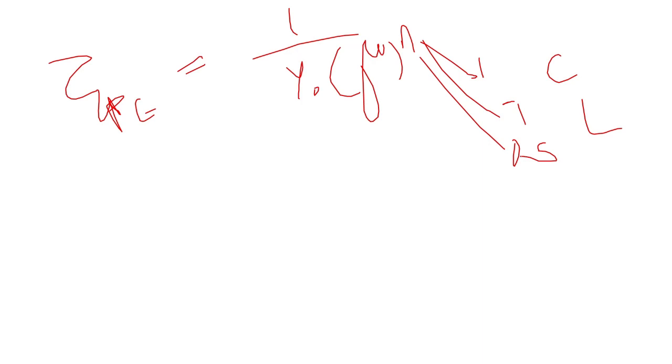In order to describe pitting corrosion, there was a model by Digby MacDonald. It gives a description of the metal film and electrolyte interface. The film will be covering the electrode surface and it is made of a metal oxide. It is a lattice that is not perfect, so it will have vacancies in it, and it will also have some cation interstitials. Because anions are large in size, we say that anion interstitials won't be present in the film.